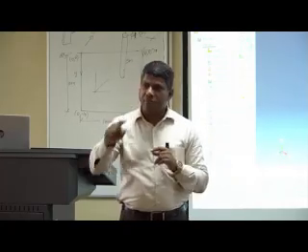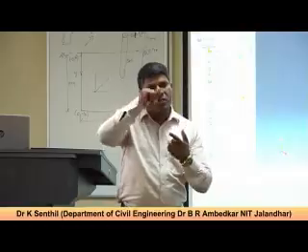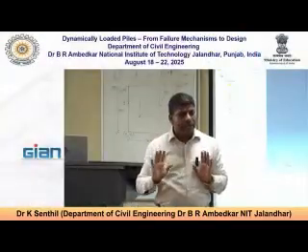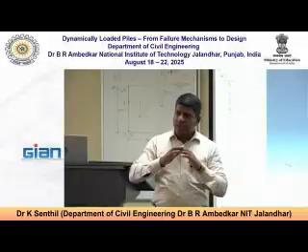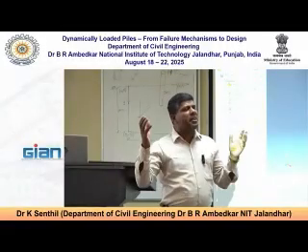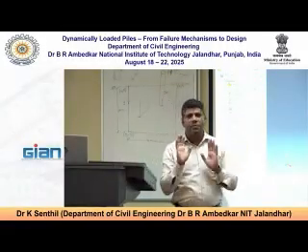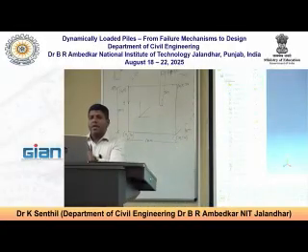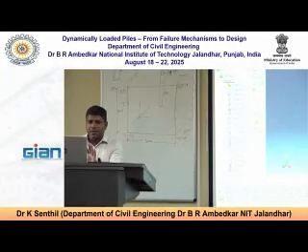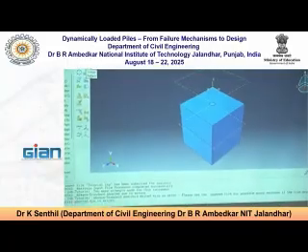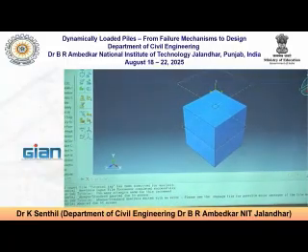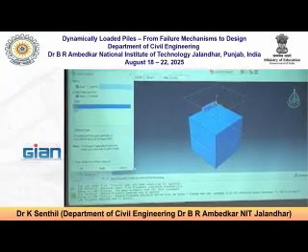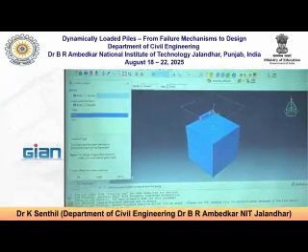Reinforcement, let's say main reinforcement, and you create one stirrups or rings, and one concrete element. That one is sufficient, and you can stretch it. Maybe you can make it 100 number, 200, 300, whatever number, it doesn't matter. Now we have one pile and a soil. You go to this particular component, you can see now another pile is there.